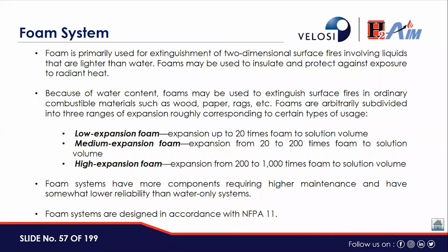Then foam system. Foam is primarily used for extinguishment of two-dimensional surface fires involving liquids that are lighter than water. Foams may be used to insulate and protect against exposure to radiant heat. Because of water content, foams may be used to extinguish surface fires in ordinary combustible materials such as wood, paper, rags, etc. Foams are arbitrarily subdivided into three ranges of expansion, roughly corresponding to certain types of usage. It involves low expansion foam, medium and high expansion foams.